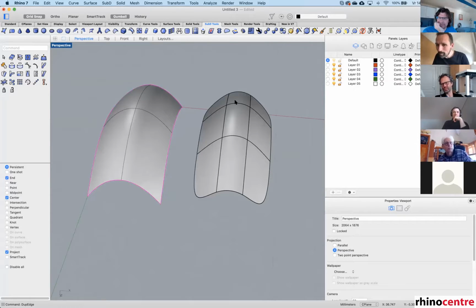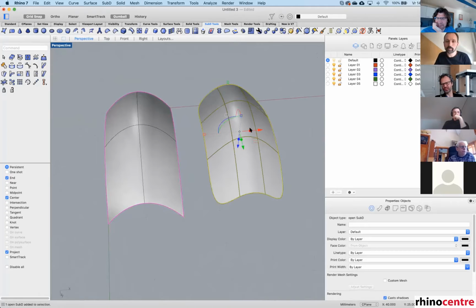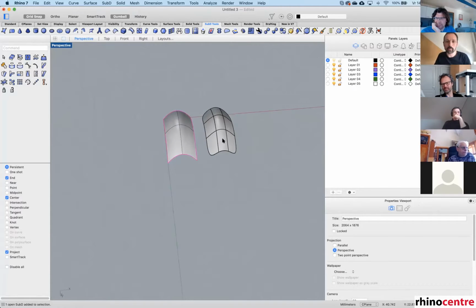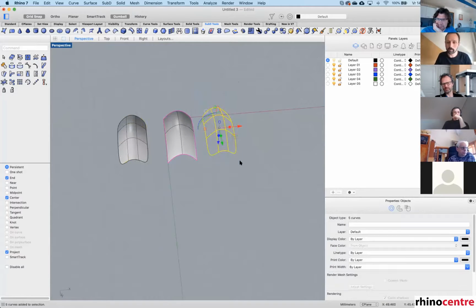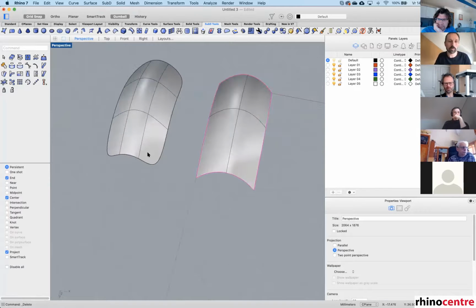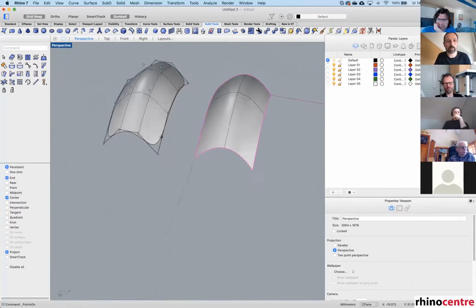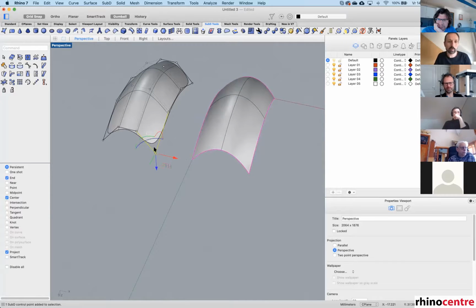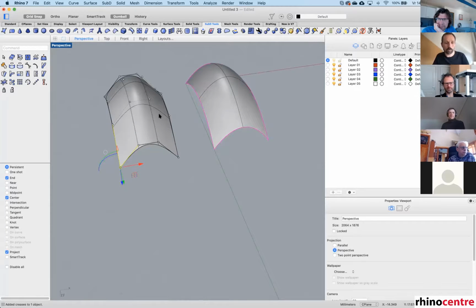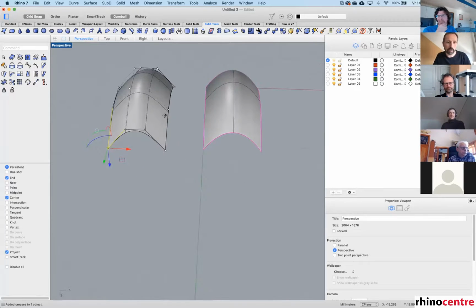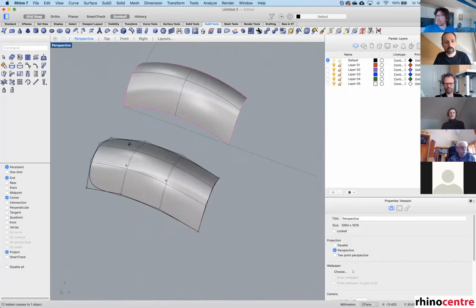The corners of your new surface, of course, are not sharp as on the Nurb. Yeah, you mean for this object they're smooth now, and this is something you can change if you want. Turning on control points for this one, right now these corners are smooth. You can turn them into sharp corners with the crease tool this way. We'll come back to creases a little bit later, but that's the way to do it.